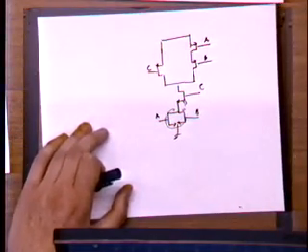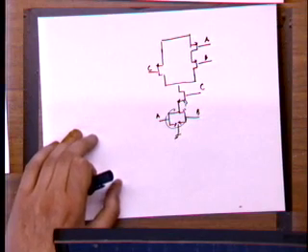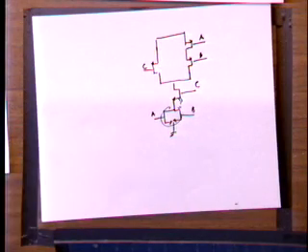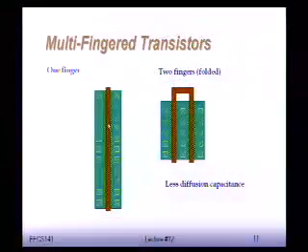So as we said, what we want to do for the transistor is try to lay them out as a single multi-finger device, right? But let me skip one slide and explain what that means. So let's say we have two transistors and we try to lay them out as a multi-finger device, okay? So I can do two of these single finger devices, or a single one of these, okay?